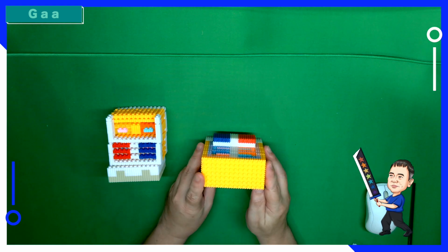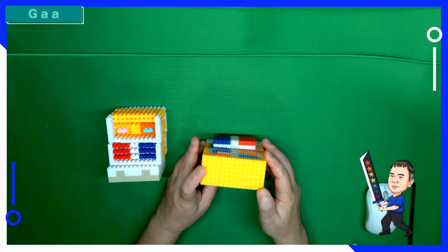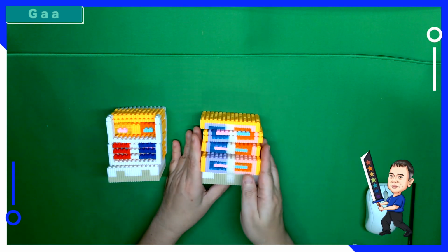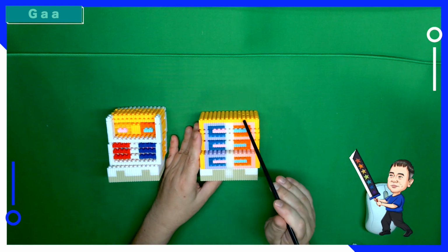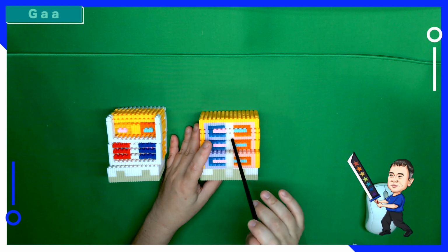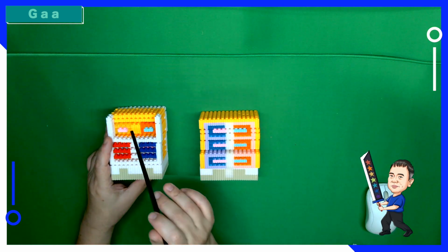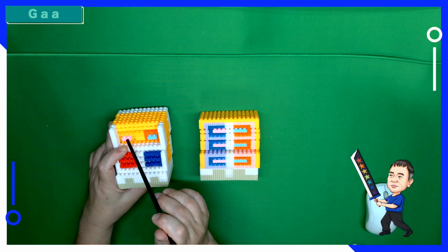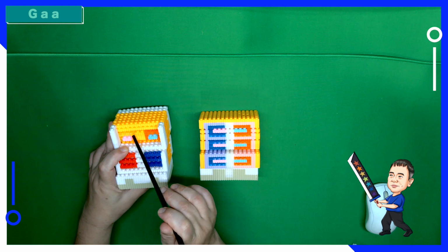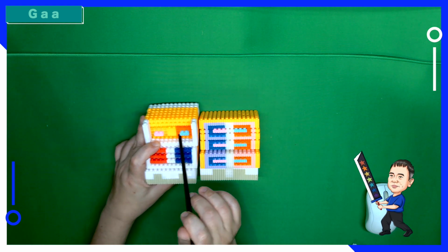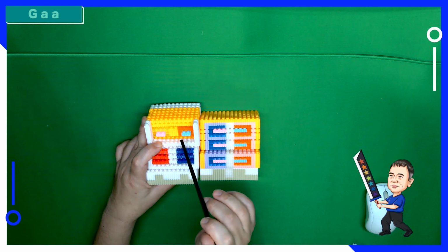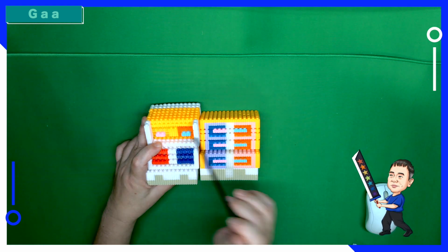Now the next one is a fork sheet complementary metal oxide semiconductor. Now the word fork comes from here. So when we look at here, it's metal oxide semiconductor, but inside here, this one is a totally insulated layer. Compared to here, between the P channel and the N channel, they have oxide, gate, and oxide. So I have oxide, gate, oxide, totally three different materials, between the N channel and P channel.